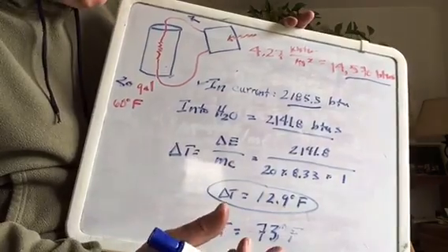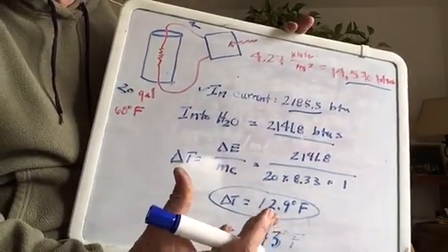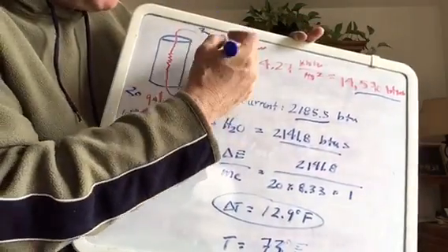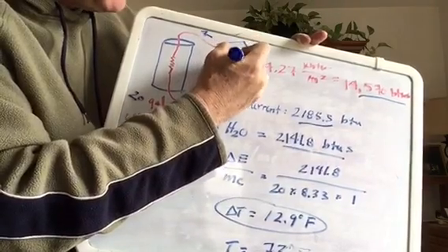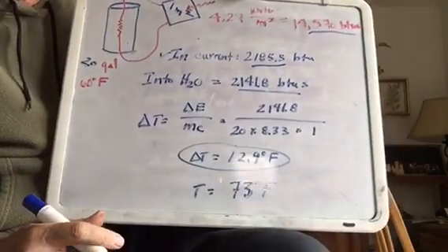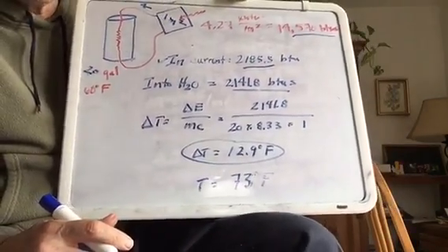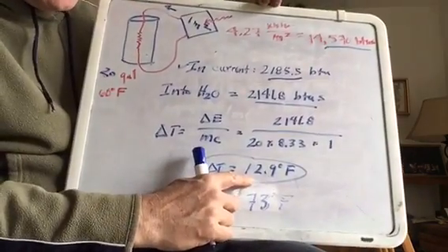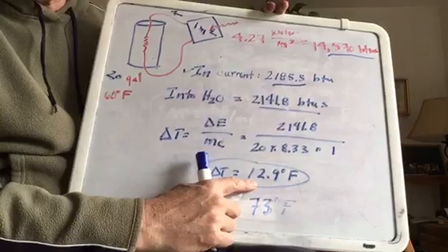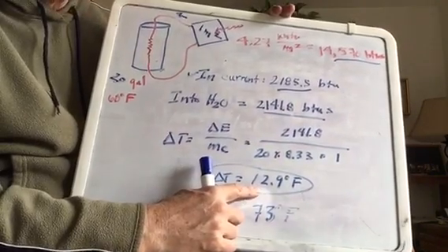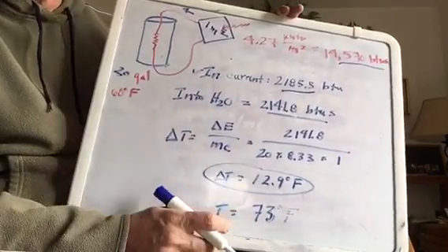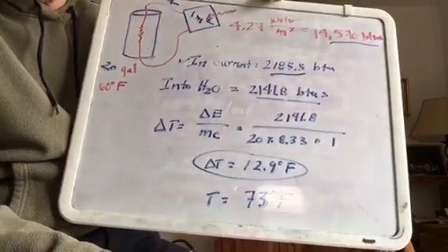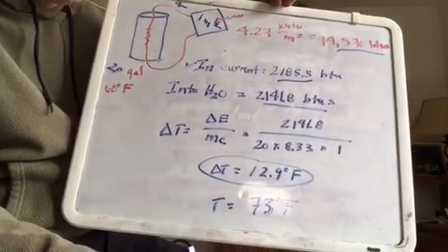So what's wrong with this? How can we fix this up? Well, first of all, if we're going to go PV, this was 1 meter squared in this example. We would need to increase the meter squared that we have, so it's going to start getting pretty large. We would like a delta T more like around 70 degrees Fahrenheit, or at least 60 degrees Fahrenheit. So we're going to need over 5 meters squared. And PV gets really big really quickly depending on how you use that.